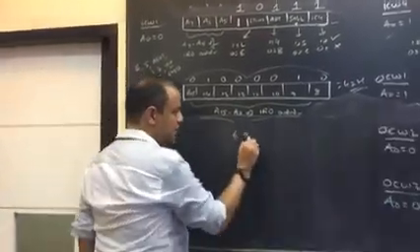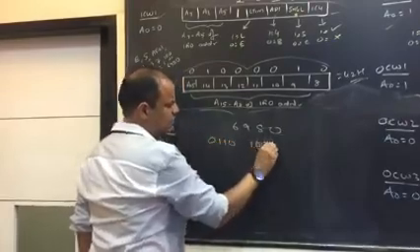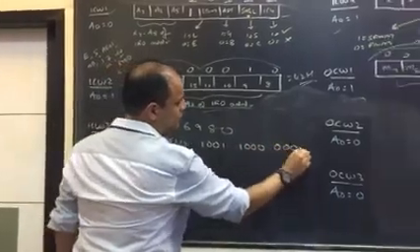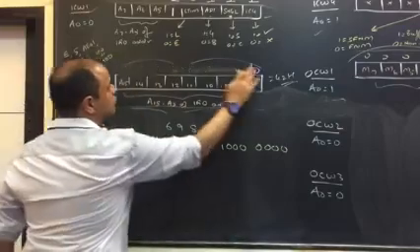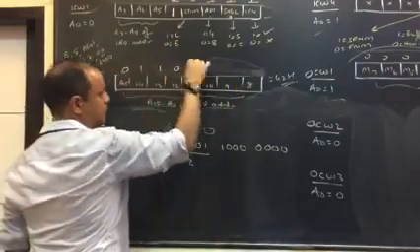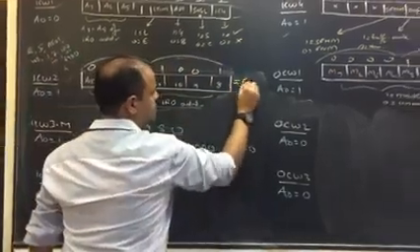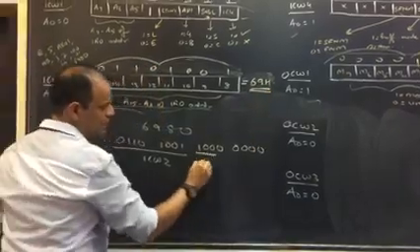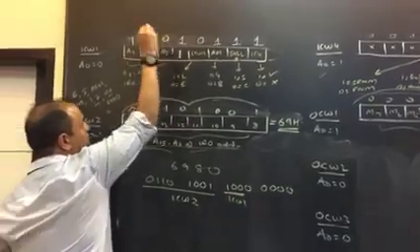Now 6980 is 0110, this is 6; 1001, that is 9; 1000 is 8; 0000 is 0. This will be given in ICW2. So ICW2 will be 0110 1001, 69H. The remaining part will be given in ICW1, so it will be 100.